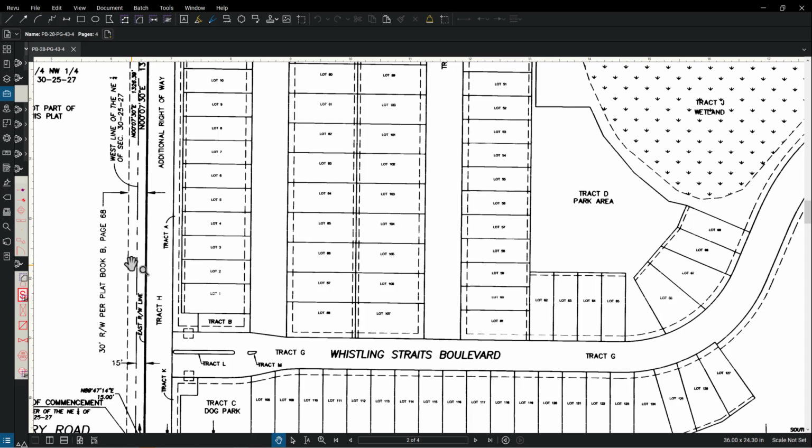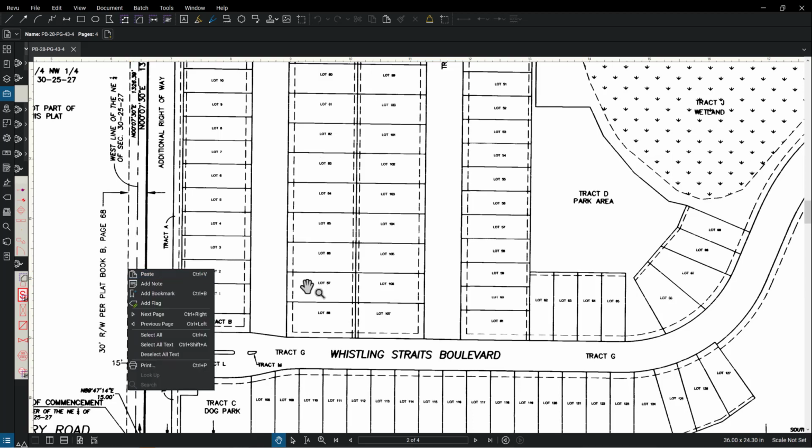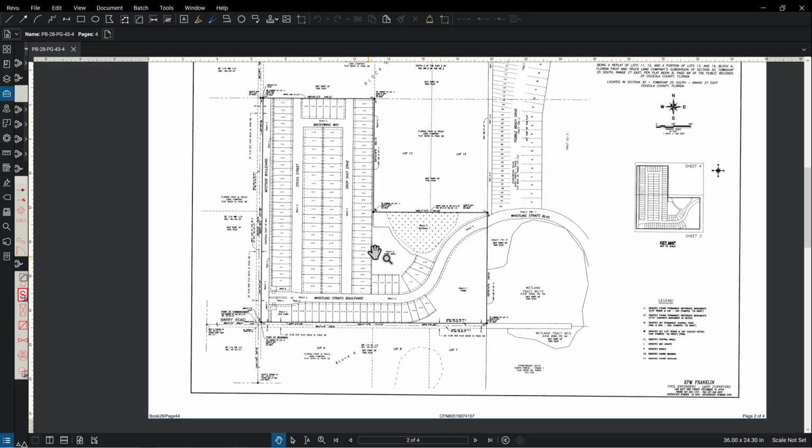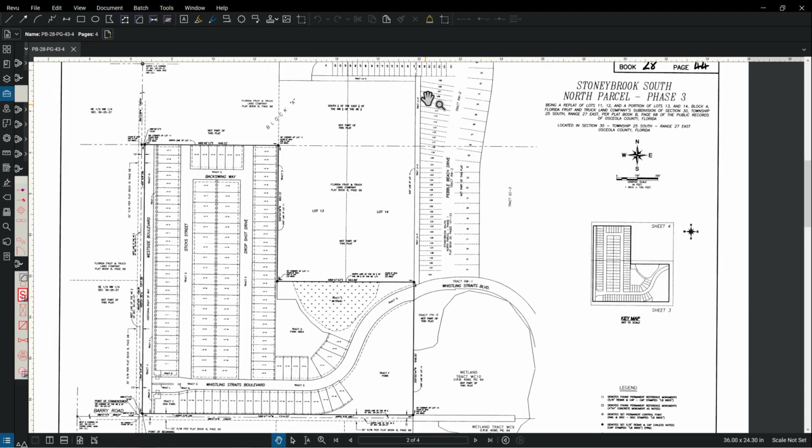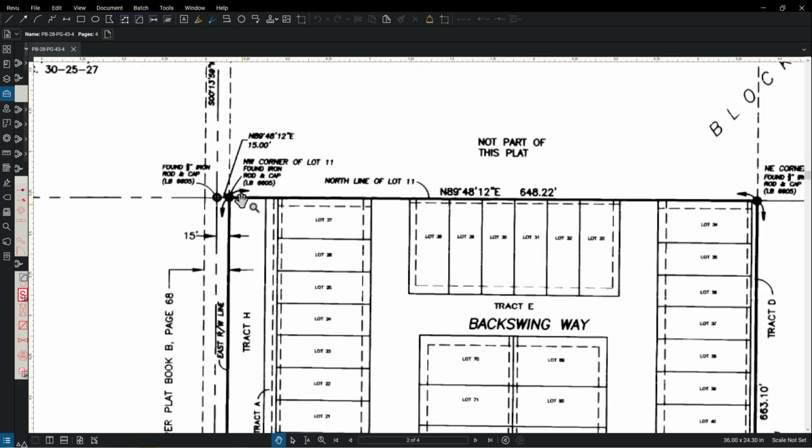Also be very conscious of the line types that you're using. So for example, this line right here is a phantom line, right? And then this is a hidden line. And then what you see on this page, I want you to mimic. Don't worry about this information over here. As we move through this exercise, like I said, I will provide you with the fill-in material. But your job is to understand what you're labeling.